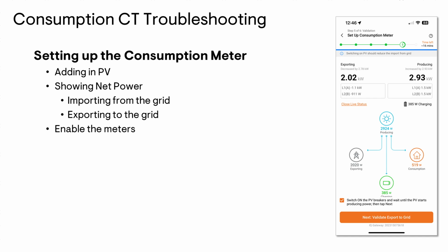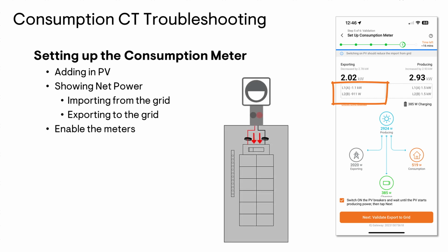What's interesting about this screen is that you won't see a negative value for your total consumption, but underneath there for the individual line 1 and L2 readings, you will see negative values only because the gateway is now reading that from the CTs. That's the raw data. And so the CTs are typically looking for current flowing in a certain direction of polarity, right, with that arrow.